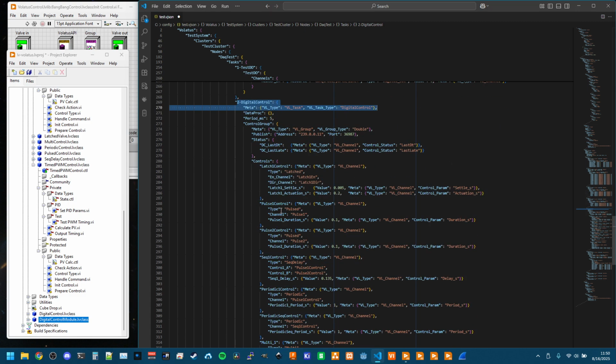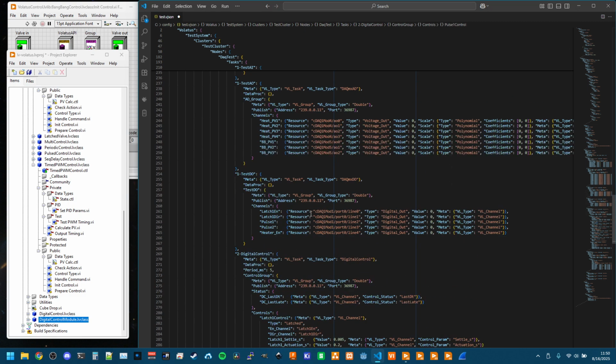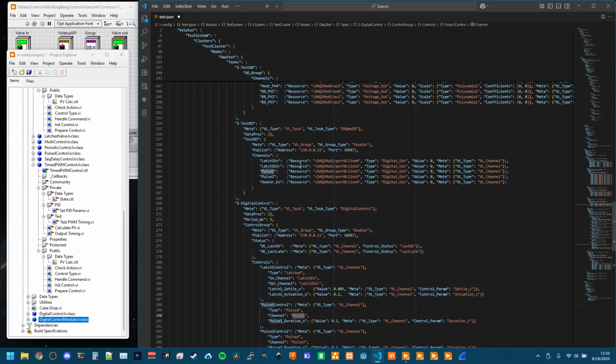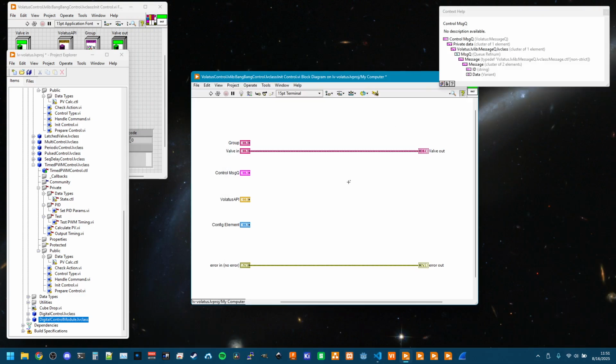It can shortcut having to look up the message queue elsewhere. A lot of these that are meant to output to digital output channels, which if I selected just the right amount of text, we see it highlight here, are going to have to do this queue lookup because it's going to know, hey, I need the queue for the module that is responsible for this channel. And there is a VI specifically for doing that lookup, so it's not like it's difficult. But we just don't need to do that. And saving a little bit of time on initialization is always good.